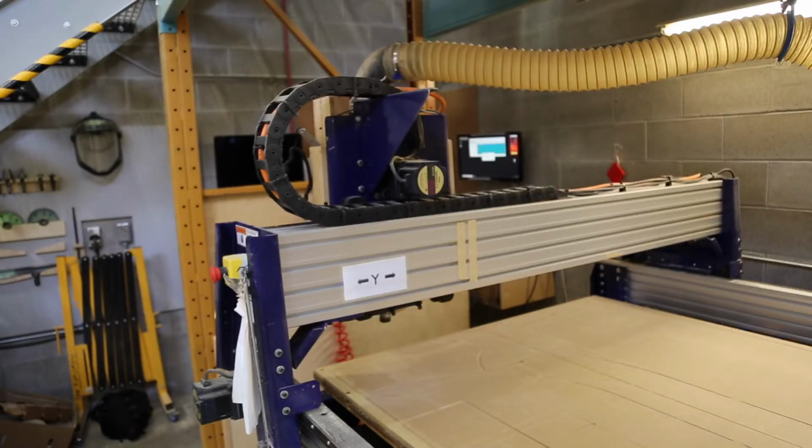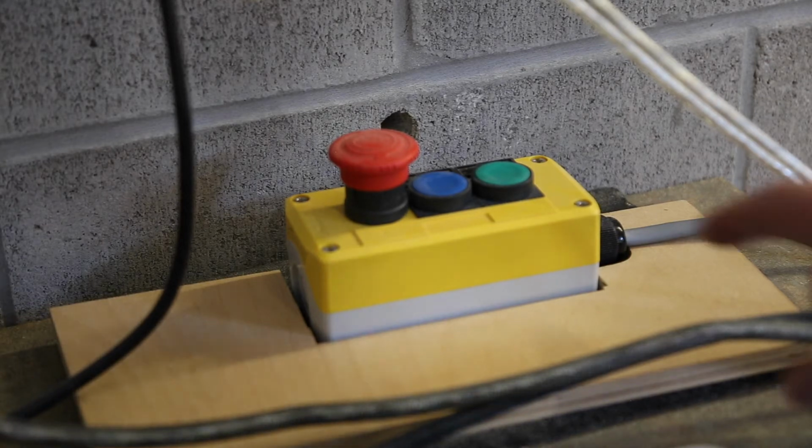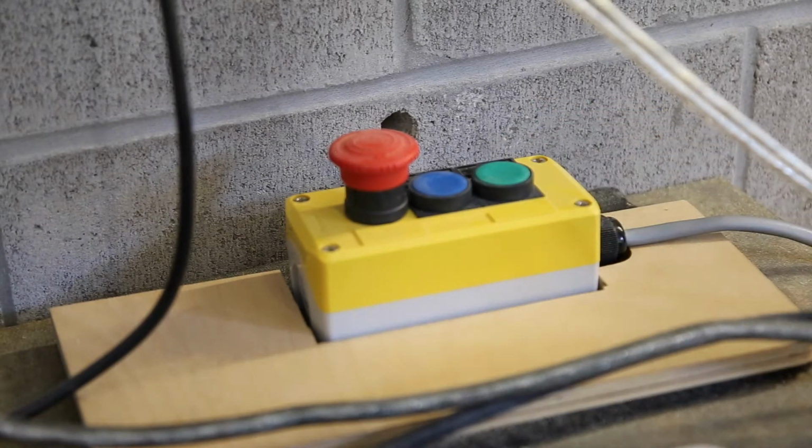Under the Cuts menu, select C5 for spindle warm-up routine with the mouse, or enter C5 in the yellow command line in the Shopbot console dialog box. Press the green Start button on the yellow remote on the top of the monitor cabinet to start the spindle. Ensure the spindle is running.